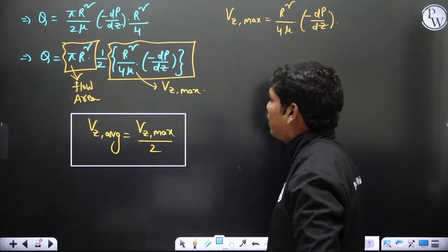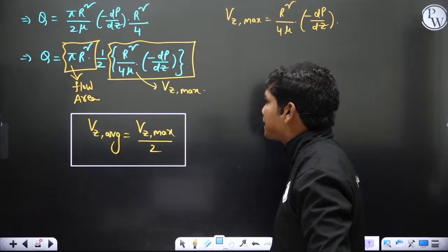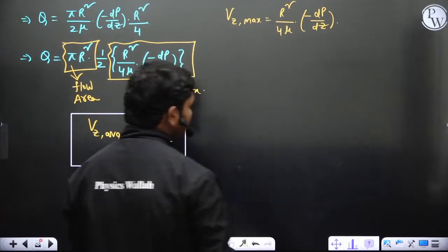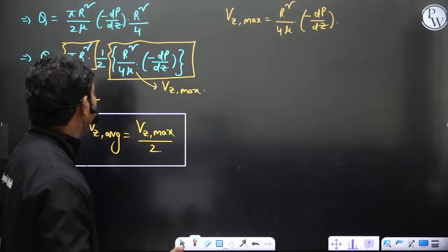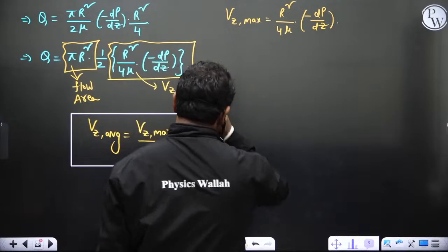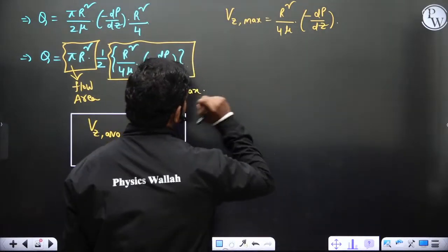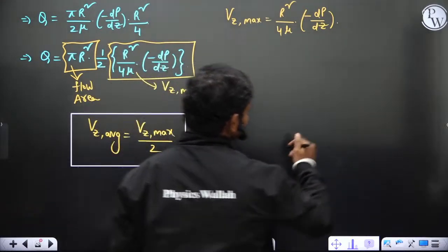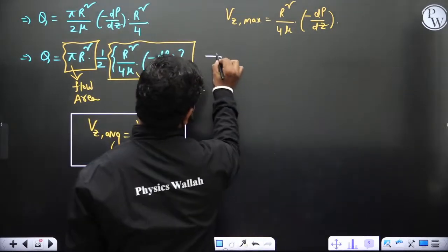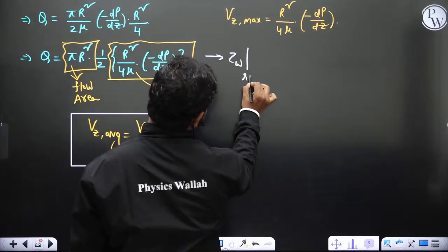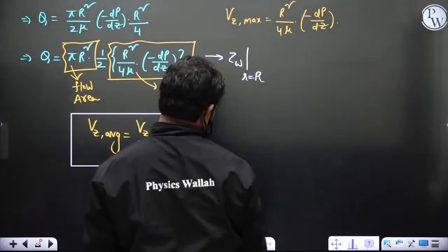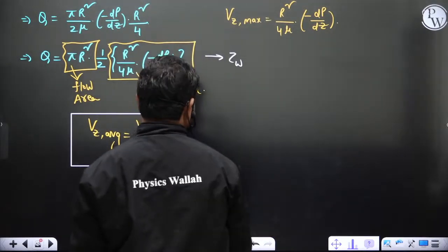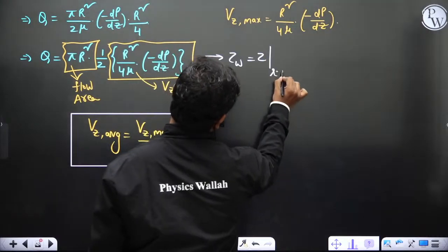So what we can do after this? Discharge is done. Fine. We'll calculate what is skin friction coefficient and friction factors. First of all, let us calculate wall shear stress. Tau W, wall is at radius is equal to capital R. Tau wall is nothing but tau at a radius is equal to capital R.